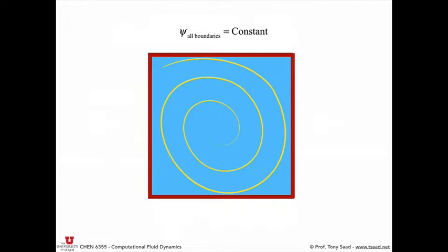All right. So now we still need to deal with the vorticity. We need boundary conditions for the vorticity because that's the vorticity transport equation, right? So for the stream function, all we needed were these boundary values. We already used the normal velocity components. Next, we're going to use the parallel velocity components to the walls to get the vorticity. Remember, when I drew the flat plate, it was the velocity parallel to the plate that gave us that vorticity. So it all makes sense.